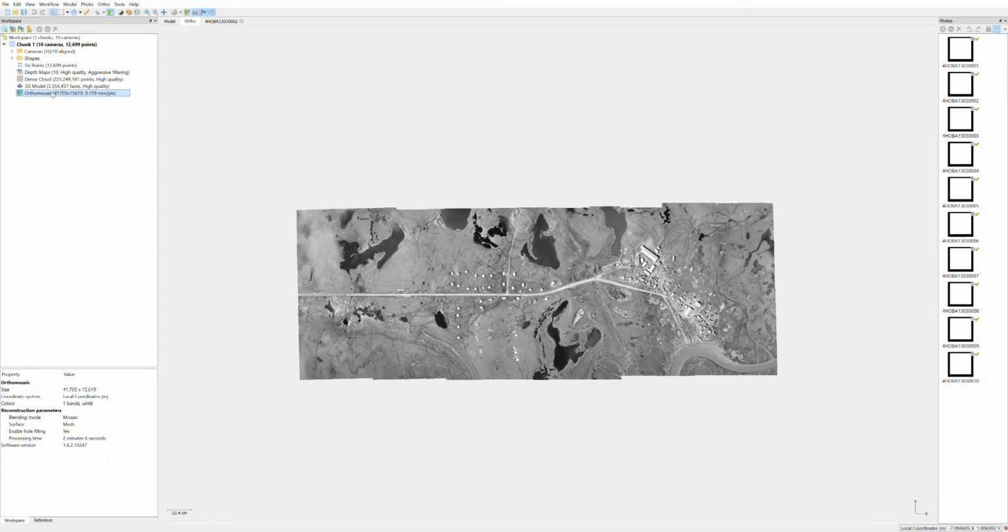And so now I will right click and export orthomosaic as JPEG/TIFF/PNG. Gives me more options. Coordinate system remains as a local coordinate system, and the pixel size here is fairly small, of course. Background color is black. So basically all this stuff should be default and you can leave it alone. We'll do TIFF compression of LZW, and that'll make any no datas not take up any space. And then don't have any of these checked on because Esri ArcGIS will take care of some of these things for us. And then when you press export, you can actually save the file.